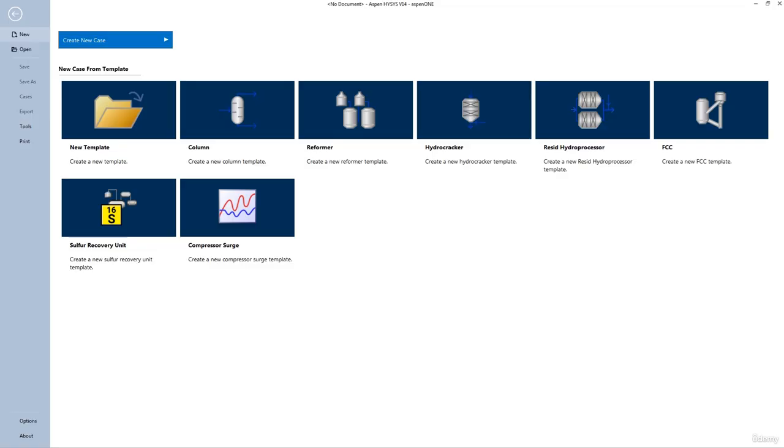Given these described species and the process conditions, the LNG process model could utilize the Peng-Robinson equation of state as its property package. This would be sufficient for most preliminary models. The PRSV method may be more suitable for a rigorous model, but this would have to be verified for each individual simulation.